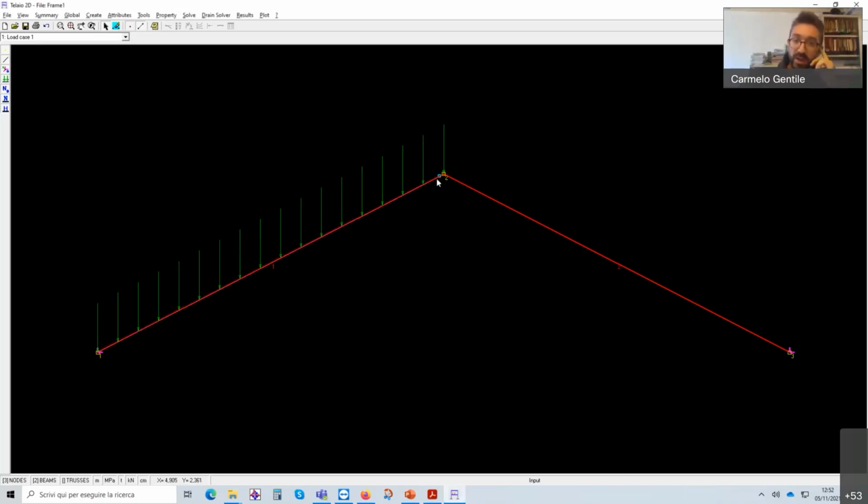And a blue circle appears close to the node 2, meaning that we are releasing something in there. Okay? We run again the analysis. Okay, this time what do we find? We find that the deformed shape is exactly what I expected and what I said before. I have deformation in the beam 1 and no deformation basically on the node 2.